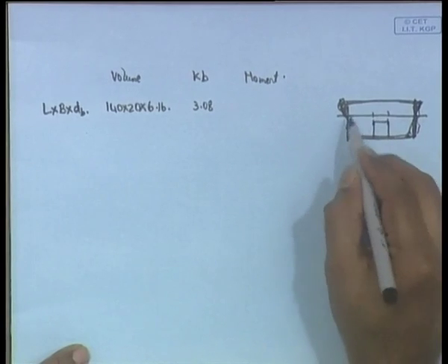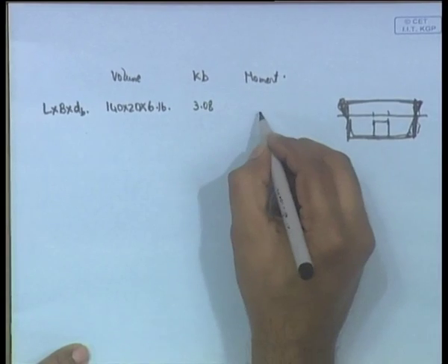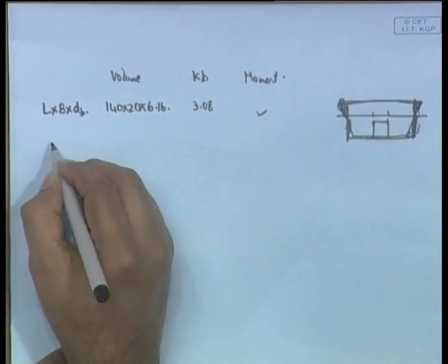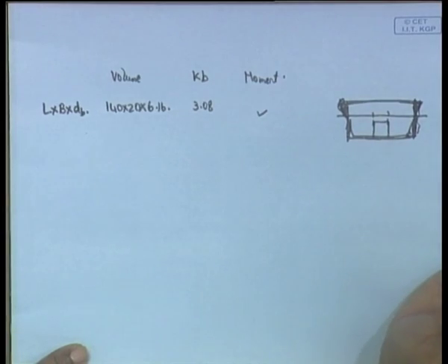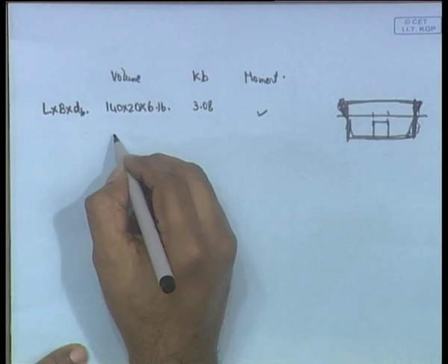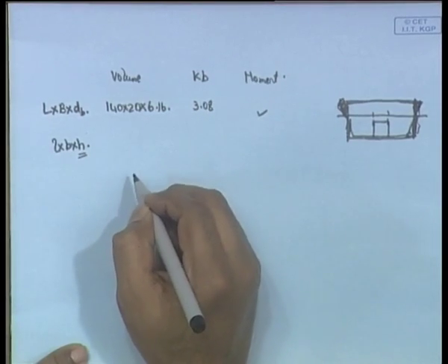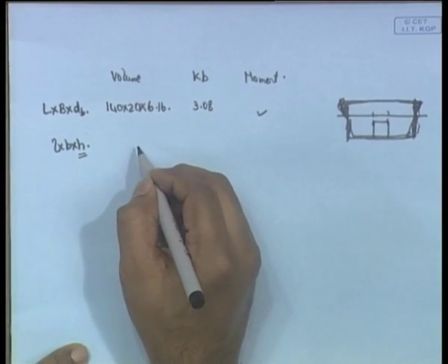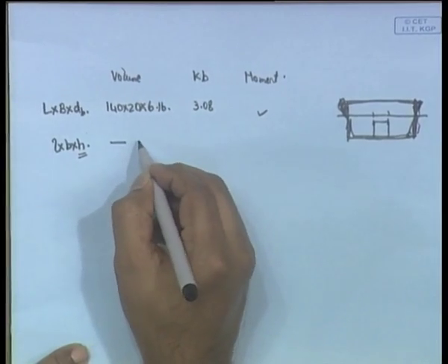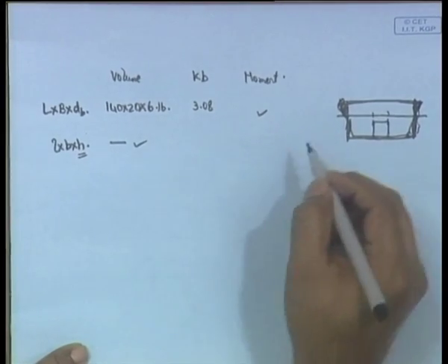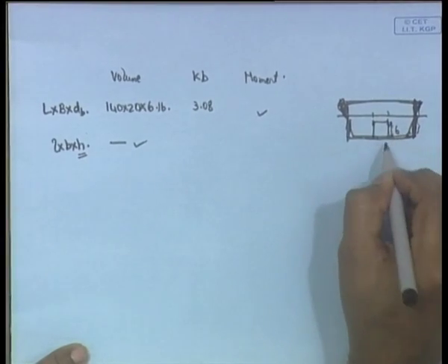So, in this case you know it's a box shape vessel. So, you know its KB, then you just multiply these two, you will find the moment. Then this volume is the volume of water entered, it is equal to the volume lost from the ship. So, this is L into B into H, remember H is the height of the flat. That you do, and the best way is to put it as negative, because this volume is lost from the ship. And the height of the flat, we have just seen, it's 6 meters. So, its KB is 3 meters.